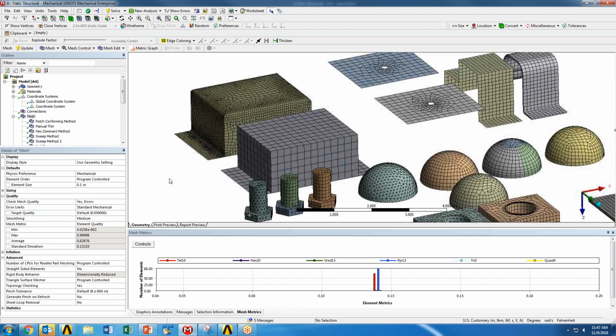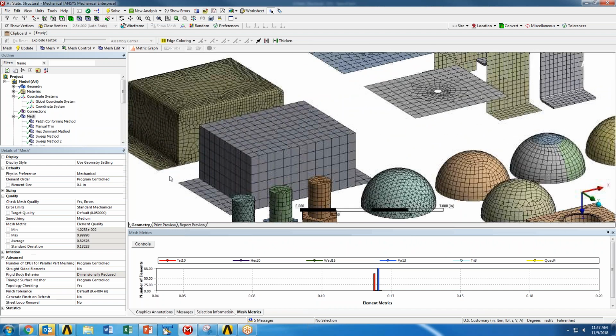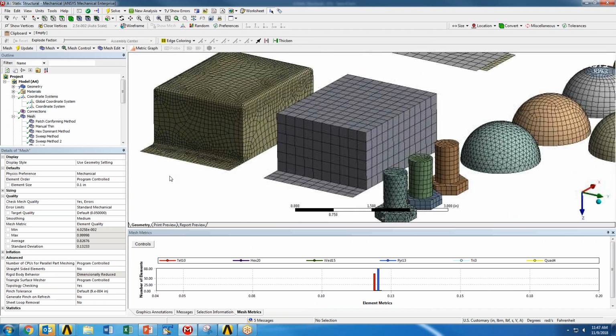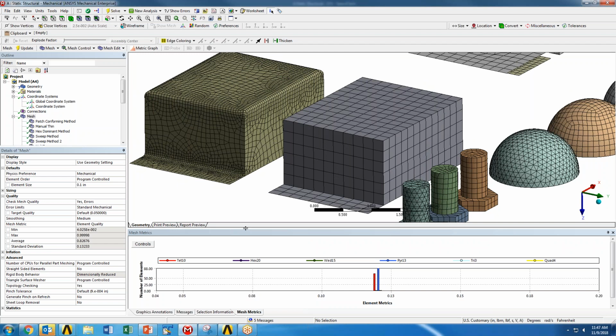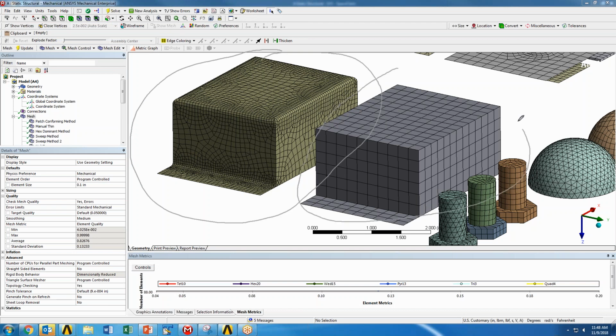Okay, so next step. If you are working in a company that generally deals with sheet metal bodies, what I recommend, if you're ever running an analysis, is that it's usually beneficial to remove radii prior to creating a surface from a sheet metal body. These two parts right here are essentially the exact same shape. However, one I left all the fillets in there, and the other I removed them.